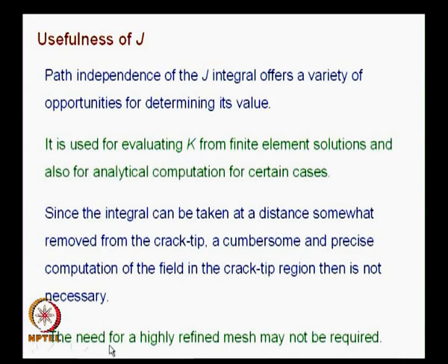And that is what is summarized here. The need for a highly refined mesh may not be required near the crack tip. So, you can attempt to solve practical problems when you have the advantage of J for you to calculate the stress intensity factor K. We say that it is path independence.